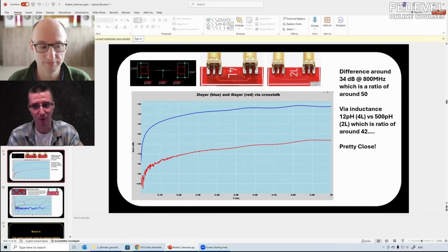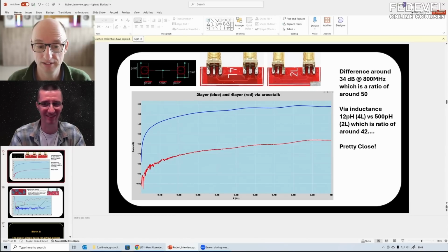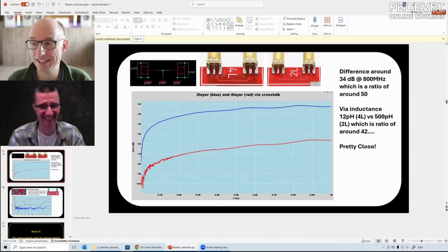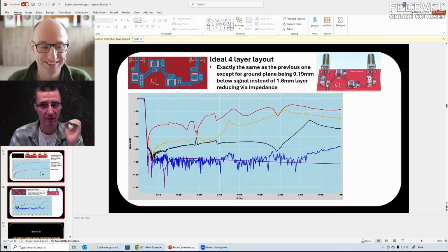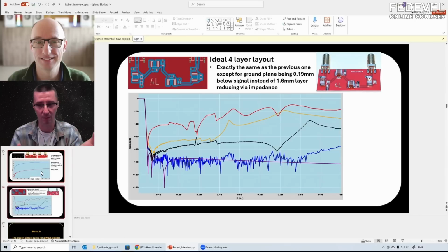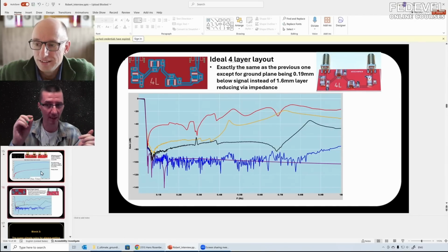Okay, and then also if you add capacitors and you already have some inductors, it can resonate at all kinds of different frequencies. Yeah. If you start looking at power supply decoupling and filtering, you open a whole other can of worms. Okay, let's move to the next slide. I don't want to confuse everyone now, but I find it interesting because I've done so many videos about power delivery, and we always stress how important the vias are in power delivery. So this was a very nice example to actually show a very simple difference between a via in a 2-layer board going from top to bottom, and a via going only between layer 1 and layer 2.